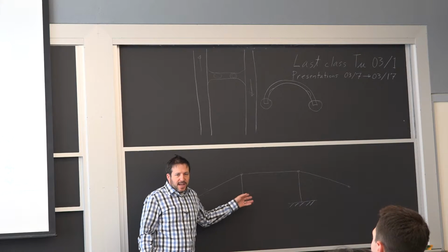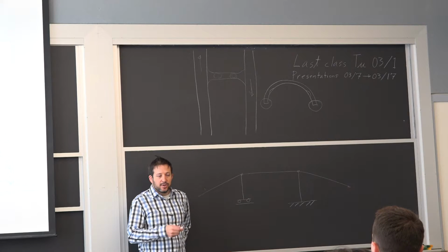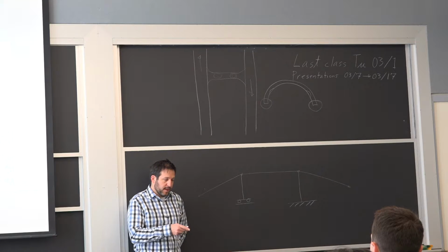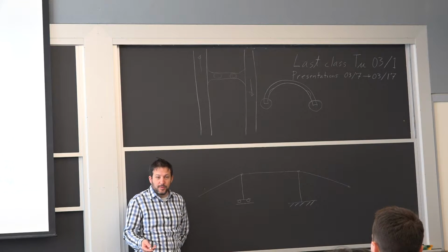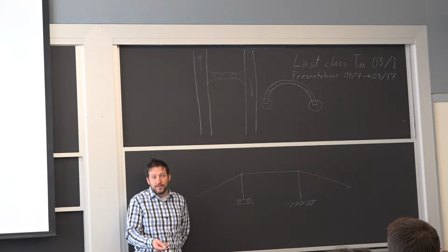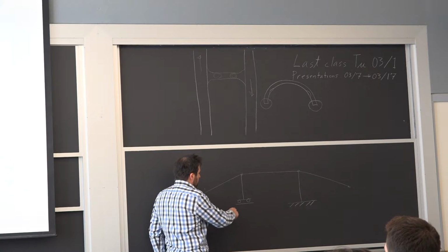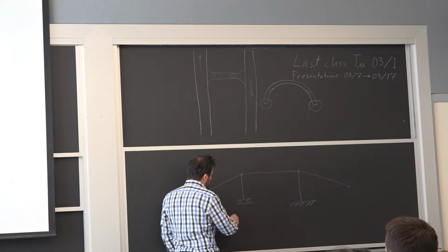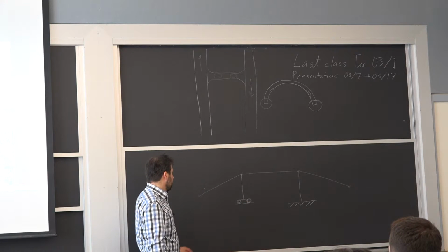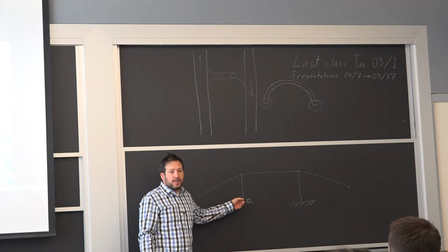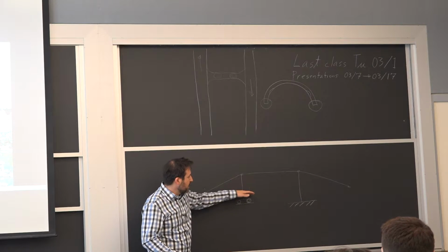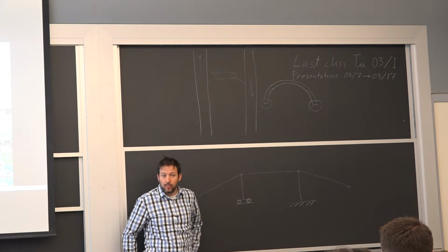It's fairly well established. So NTSB, the National Transportation Safety Board, got involved to analyze this failure because it was very consequential. It wasn't at peak traffic hours, but at peak traffic hours, you just don't want it to fall. So what they were able to observe, and it wasn't maybe emphasized as much as I wish it did, is there was packed rust in this expansion joint. So the roller system to allow this entire section to move back and forth was not working.